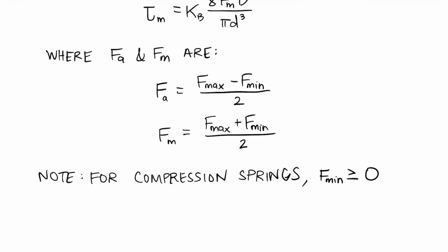I shouldn't say unloaded. Even in its minimum force condition, it still has some compressive load on it. And this is true for your ballpoint pen, for example. When you place the spring inside of your pen and you screw the tip back on, you'll notice that the spring gets compressed just a little bit. So even in its unpressed condition, you still have some compressive load on that spring.